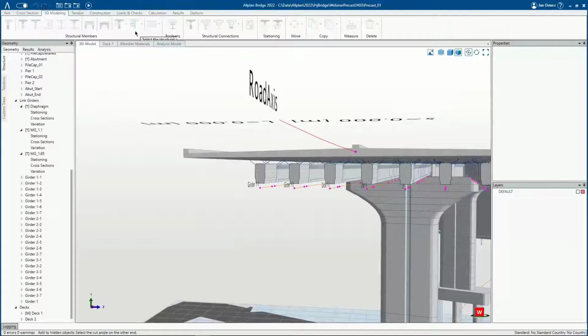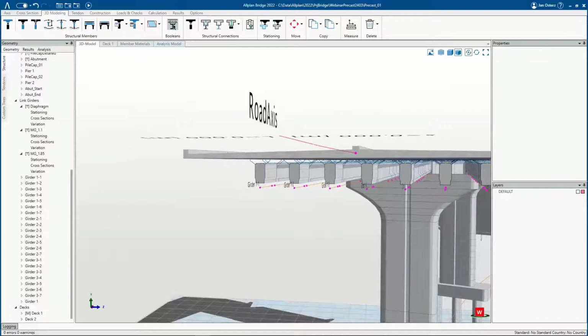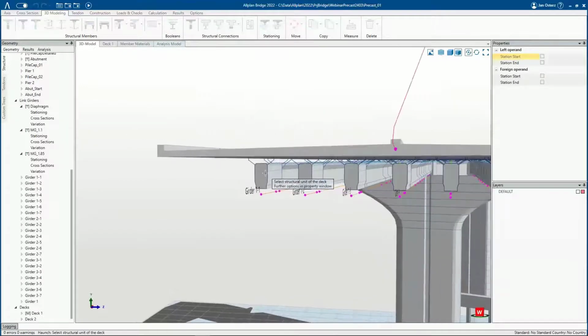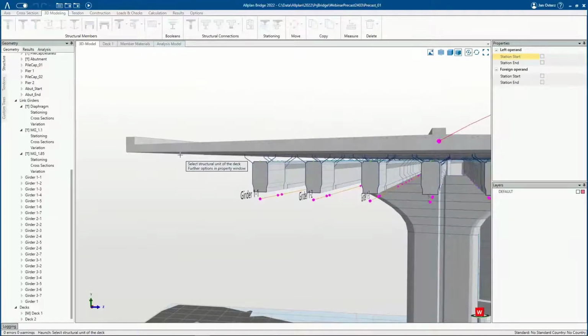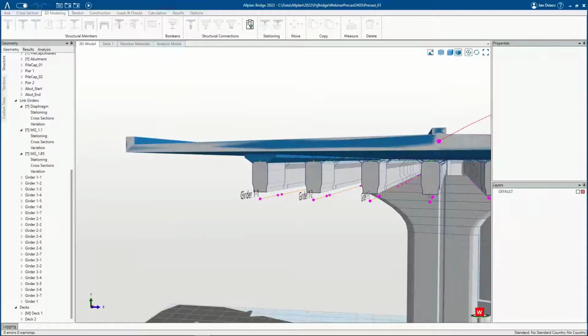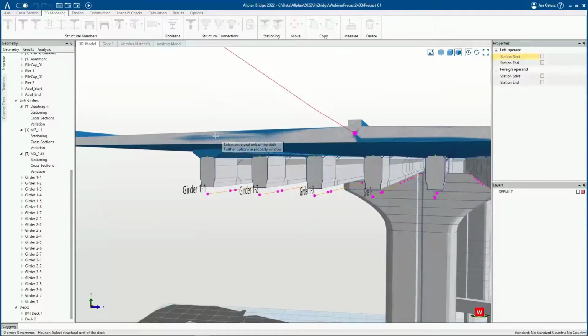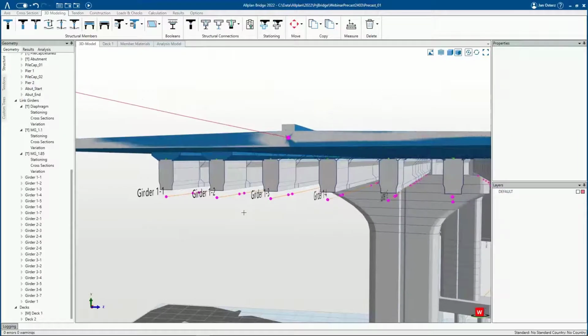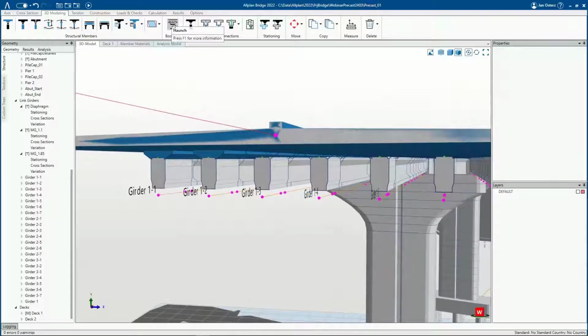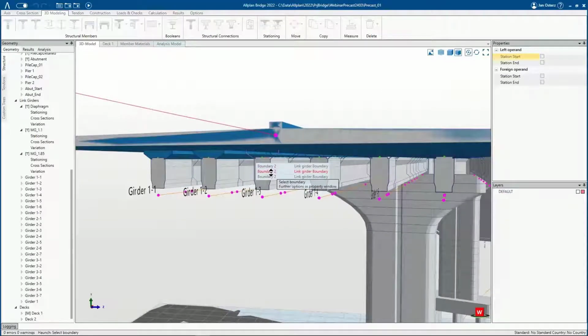So select this, go to the 3D modeling, and select the Booleans. And I just do this with 2 clicks. So I select the deck, and then I select the assigned cross-section. And we see that the haunch geometry has been formed. Go again, Booleans, here, select the correct one. And it's the second one, and we see how this void or this gap is now filled.